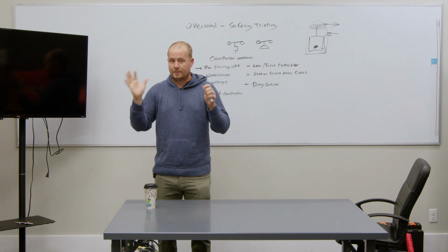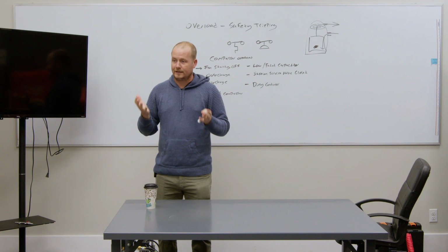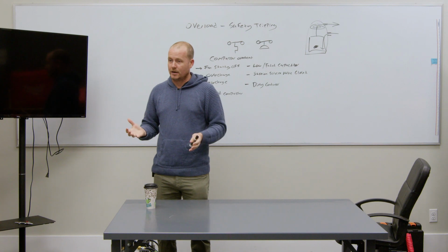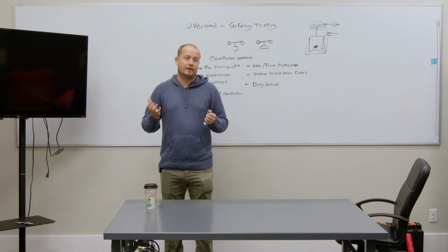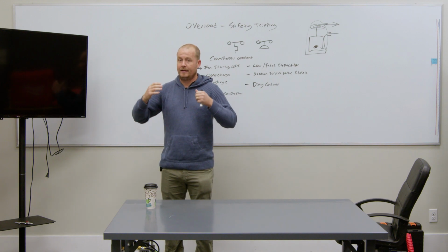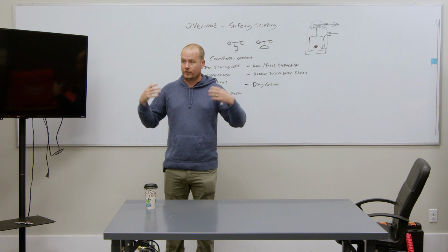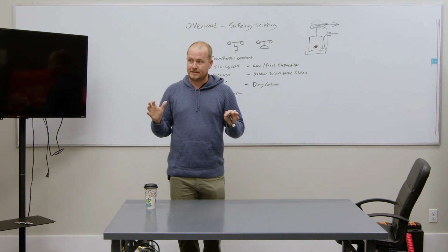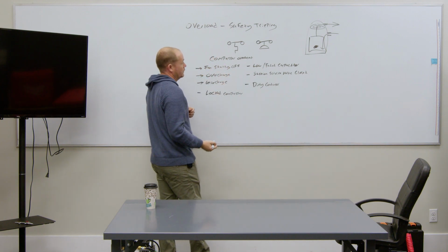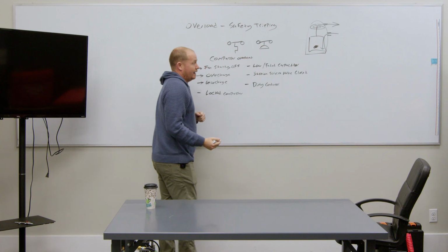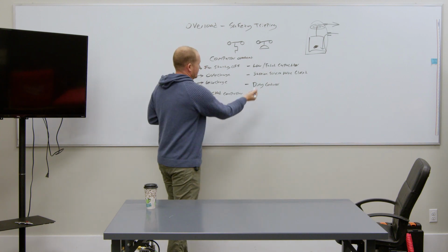So the point being, what I'm getting at here is you can actually tell a little bit about what might be going on just by how quickly it's resetting. If you have a compressor that's taking forever to reset that thermal overload, that's an indication that it was a running fault, meaning that it sat there and it was running for a long time, and that entire shell was getting hot, and all that thermal mass heated up. Make sense? So things like fan shutting off, overcharge, undercharge, suction service valve closed, still has to heat up the whole inside of the compressor, dirty condenser.